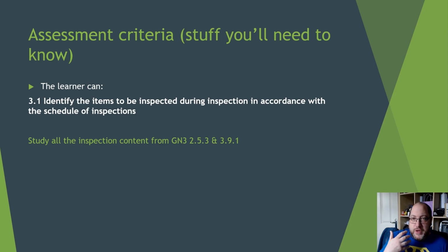So the obvious thing is you need to understand what inspections to carry out, and your general knowledge on all electrical systems is important here. You may be asked a question on your inspection for a steel conduit system. If you've never installed a steel conduit system, it's worth developing a bit more understanding on the system so you can understand what inspections you'll need to make, because you can't really be certified as being competent to inspect steel conduit if you've never really worked with it. So think about any other development you may need, theoretically and practically as well, at the same time here.